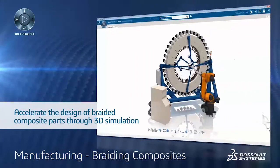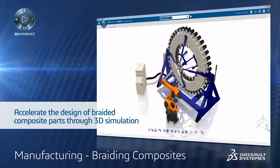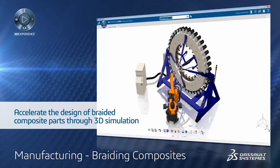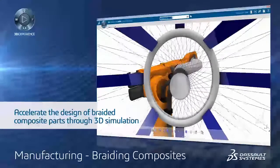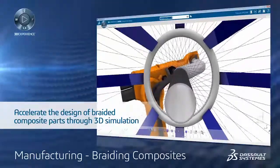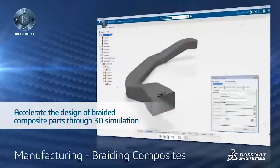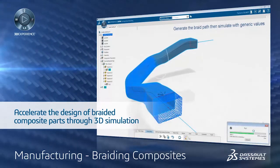To accelerate the design of 3D braided composite parts, we have a unique solution that provides advanced fiber braiding simulation. It allows designers to define and visualize fiber paths on complex surfaces and optimize machine parameters to achieve the desired fiber orientations and mandrel generation to guarantee correct fiber volume and minimize mass.